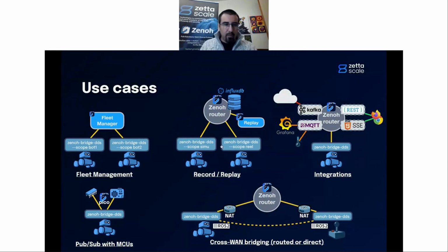You can also, leveraging some storages, and more specifically the InfluxDB storage that is able to store a history of publications, develop a record and replay environment. For instance, you can have a simulation robot to which you publish some twist messages. The twist messages are also received by the storage on InfluxDB, which stores them in the InfluxDB time series database.